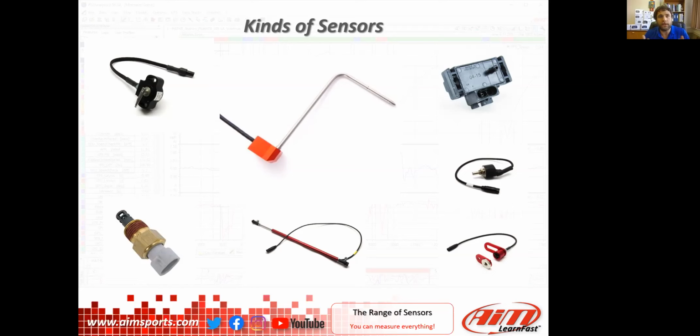And I see some of the questions popping up about these is resolution in the sensor. Well, the easy way to answer this is the more range of a sensor we use in that 0 to 5 volt, the more range of the output we get, because that's an analog signal. The 0 to 5 volts gets converted to a digital signal, and then it gets put through to the positions or other things through the analog to digital converter. It gets a little bit more in depth than what we're going to see here, but the more voltage range that we have, the more resolution we have out of it.